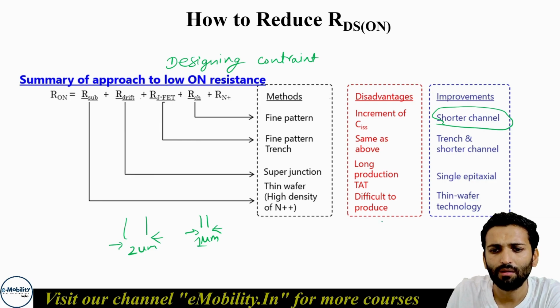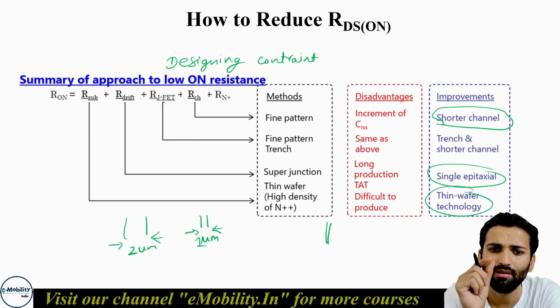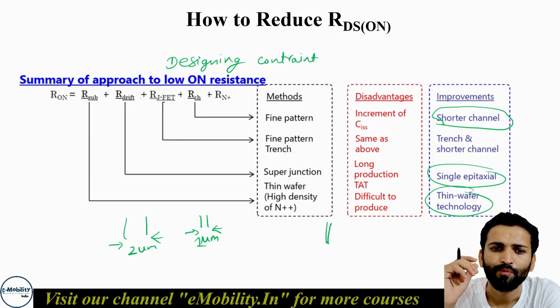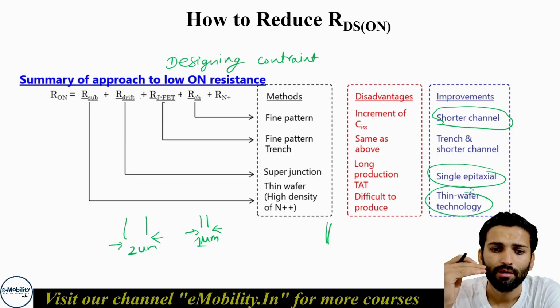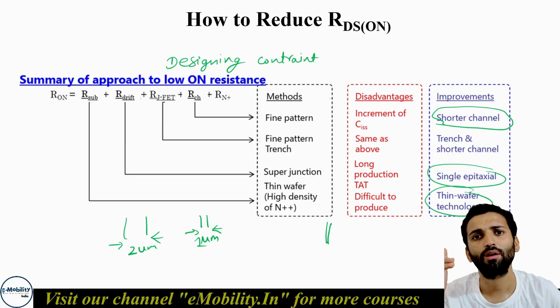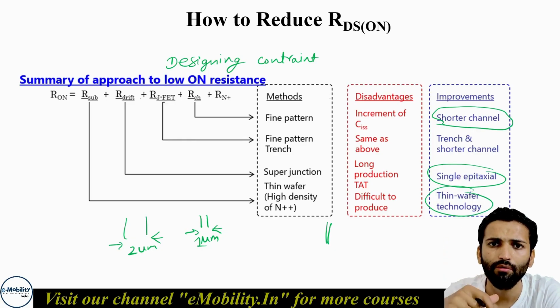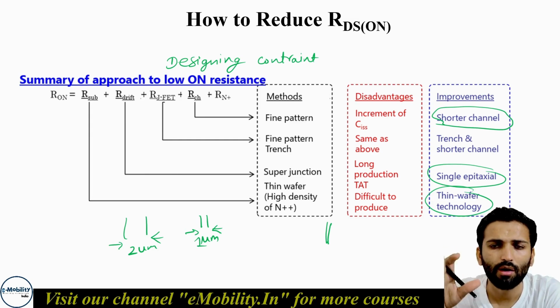Similarly, there are many things which the company does. Thin wafer technology, where the wafer size is very thin. The wafer means the silicon wafer or the semiconductor wafer. If there is a thin wafer, the resistance drops. So this is how the companies are approaching RDS on, because it is one of the single biggest factors, apart from the switching frequency, creating a bottleneck to the efficiency. So if a converter is working at 95% efficiency and you reduce the RDS on to half, the efficiency can be increased from 95 to 96 or 97%. So this is how important RDS on is.